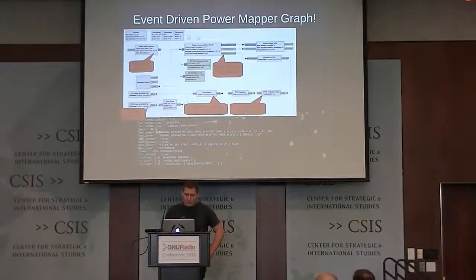So what we're doing here is I have a stream of samples coming in from a USRP. And then here I'm doing a trigger which is not based on anything happening in the signal, because FM broadcast is just always on, right? The stream, it's not really an event thing. But what I want to do is map received signal strength. So if I'm WAMU, I might want to know my subscriber coverage. Where can people listen to my radio station and get good reception, right? Are there badly faded areas that I need to care about or not?